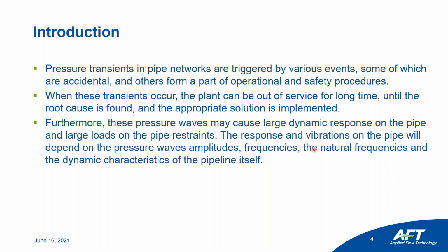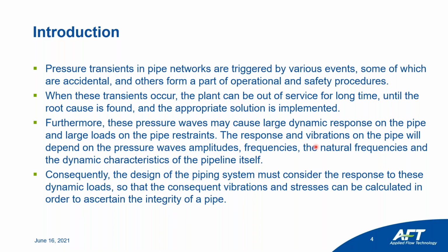Furthermore, these pressure waves may cause large dynamic response on the pipe and large loads on the pipe restraints. The response and vibration on the pipe will depend on the pressure wave amplitude, frequencies, the natural frequencies, and the dynamic characteristics of the pipe itself. Consequently, the design of the piping system must consider the response to these dynamic loads, so the consequent vibration and stresses can be calculated in order to ascertain the integrity of the pipe.